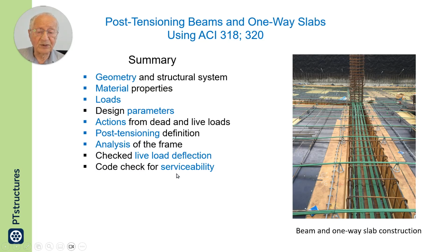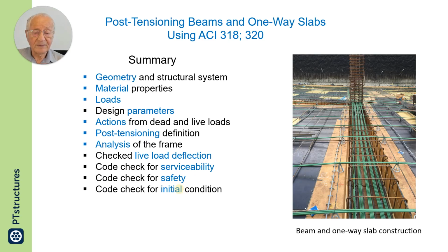Then we checked for serviceability, minimum requirements, minimum rebar, and followed it with a safety check. In safety check, I emphasized that we calculate the capacity of each section and compare it with demand.